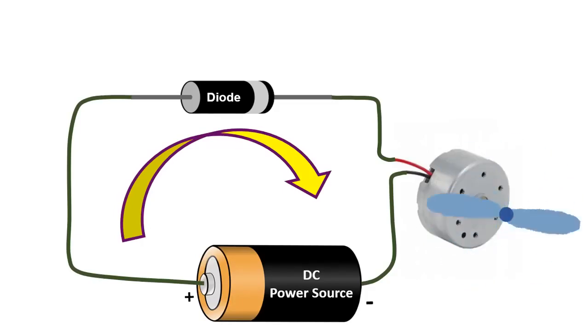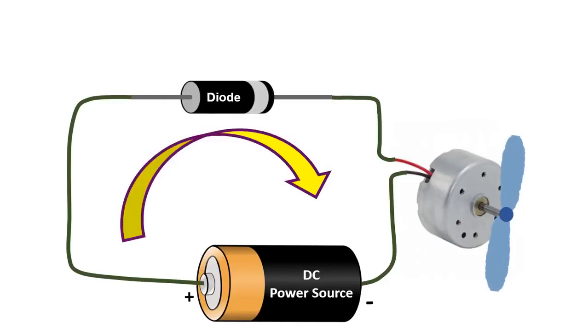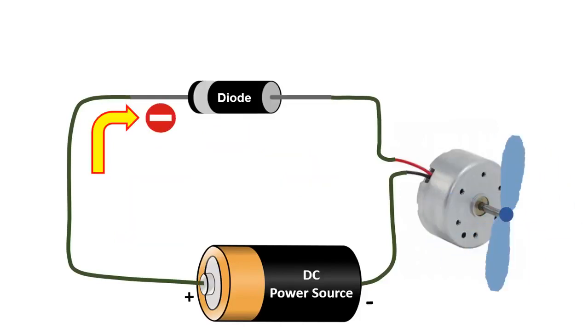The line is the side which is connected to ground, and the bottom of the triangle connects to power. Another thing to keep in mind is that it requires energy to pass through a diode, and this results in a drop of voltage. This is typically a loss of about 0.7 volts. This is important to keep in mind for later when we talk about a special form of diodes called LEDs.